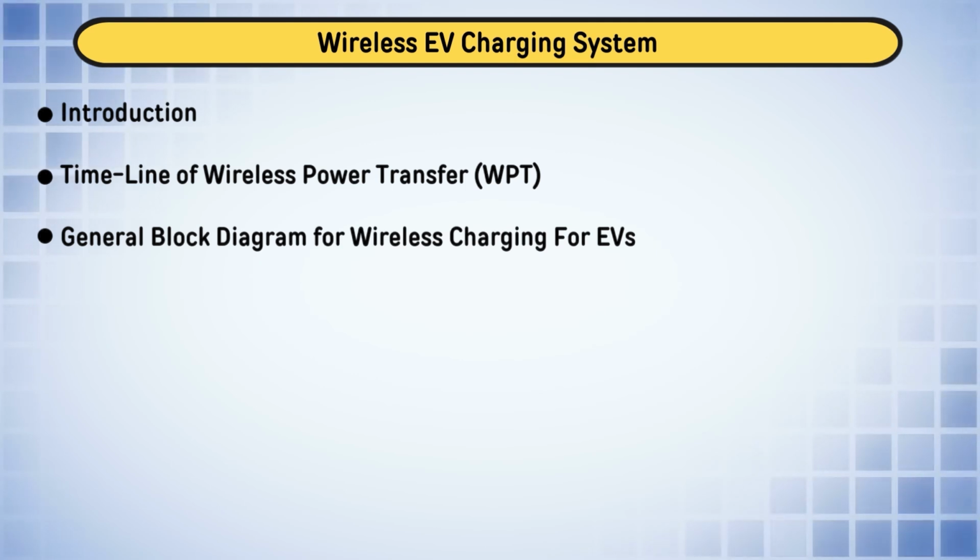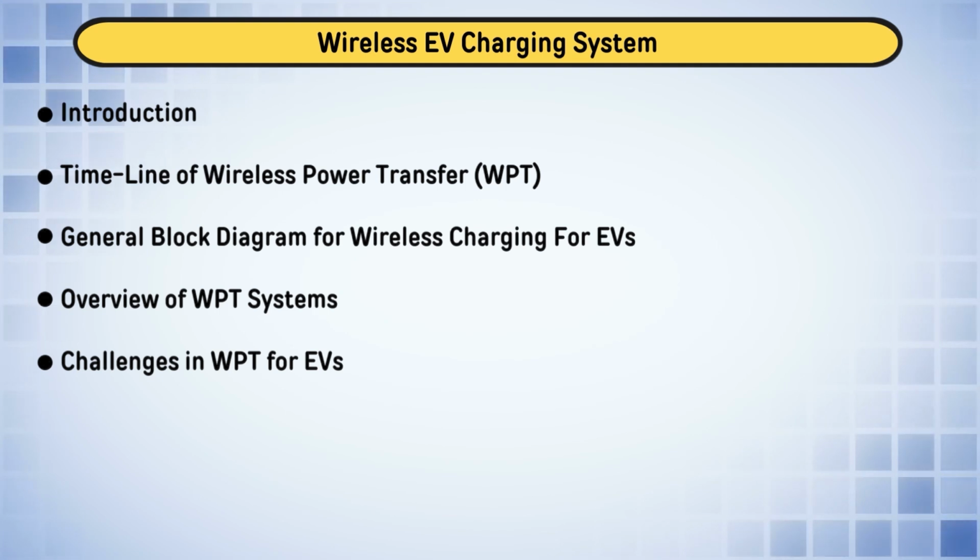We will see charging modes, how we are switching from constant current to constant voltage, then a few control strategies. Then we will see the design, control and implementation of the dual active bridge converter for EV charging. What is the design, what is the control, how the power is transferred from primary to secondary, or from input to output as well as from output to input.